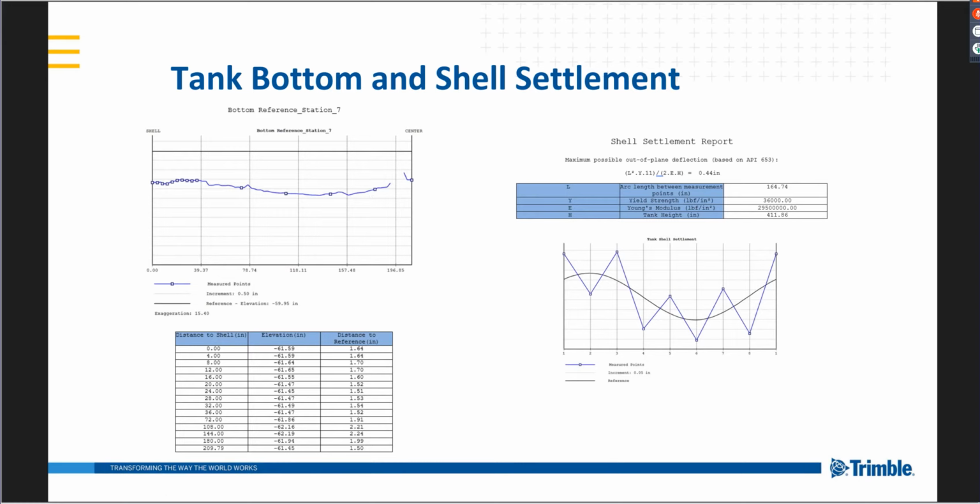Now, the reason we have these like this is we know most people are familiar with looking at traditional tank inspection reports. So we're handling all the traditional ways of viewing it and the way the standards are built. And in addition, we give you these extra tools to go in and analyze and look at the entire tank surface, the bottom or the shells, so that you can make more decisions. So just to make that clear, we're trying to follow the standards, API in particular, as close as possible, knowing that you'll also use additional tools to get the maximum value out of your laser scanner.